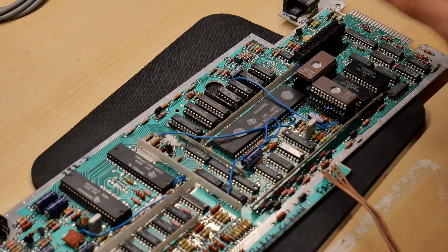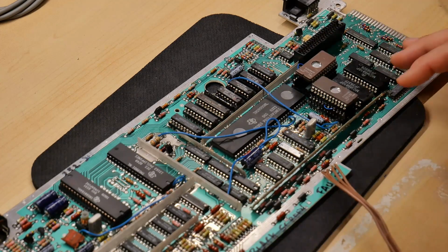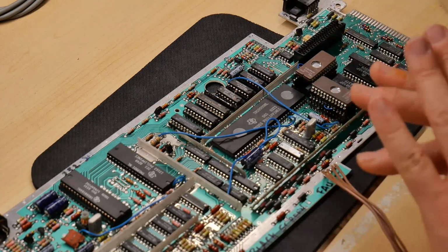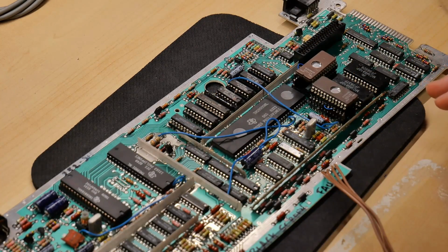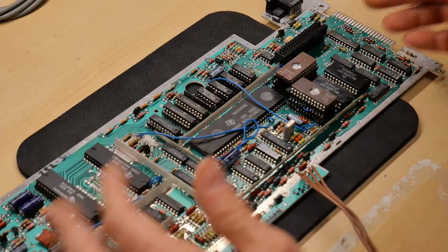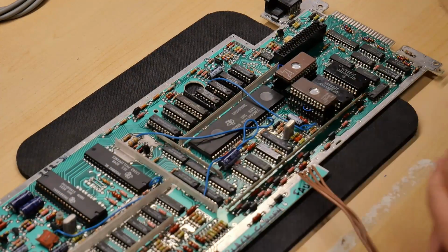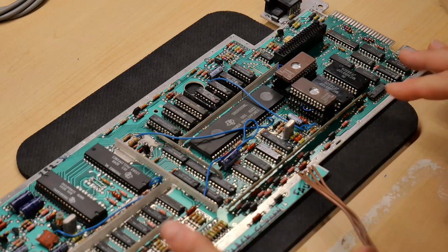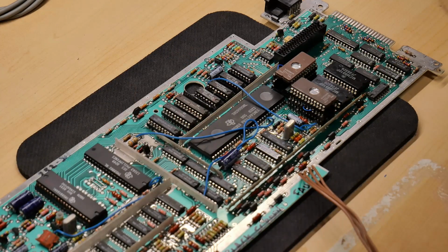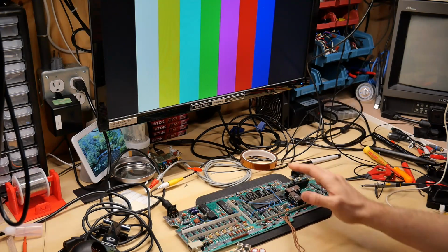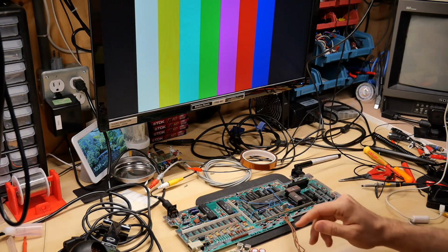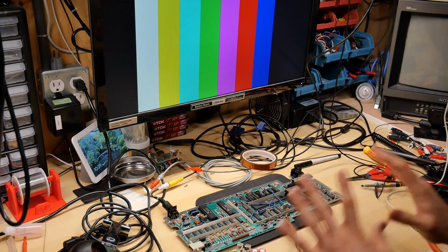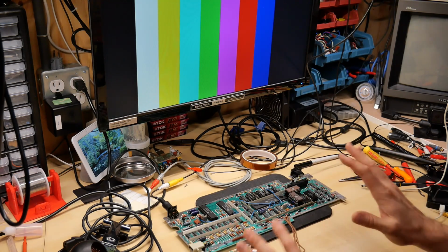I've installed the 3 GROM chips in here and the 2 stacked EEPROMs. I put the GROMs in just in case it does boot. I want it to go all the way to the boot screen. I'm not totally holding my breath because it seems like everything I do, I come across a new fault. But hey, it might work, right? Okay, we're ready to power it on. Now, if it doesn't work, it could be the 2 ROMs are in the wrong sockets. I need to swap them. So don't jump to immediate bad conclusions if it doesn't work.